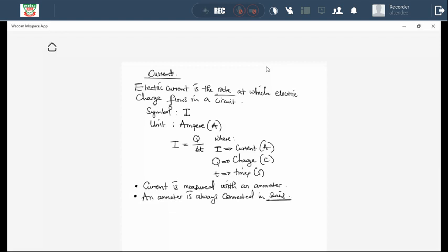It is because it needs to measure that which flows through a circuit, which is current. And it's easier for an ammeter to be connected in series because remember, an ammeter has very low resistance, so it is not going to interfere with the amount of current that flows in a particular second. So an ammeter is always connected in series.